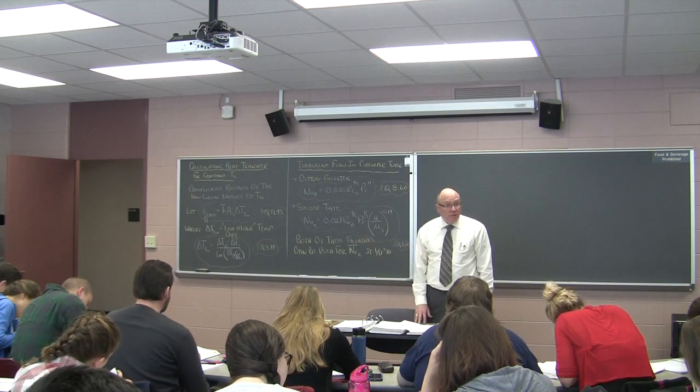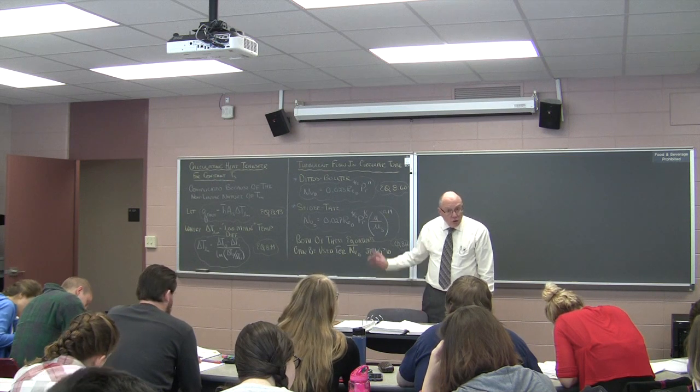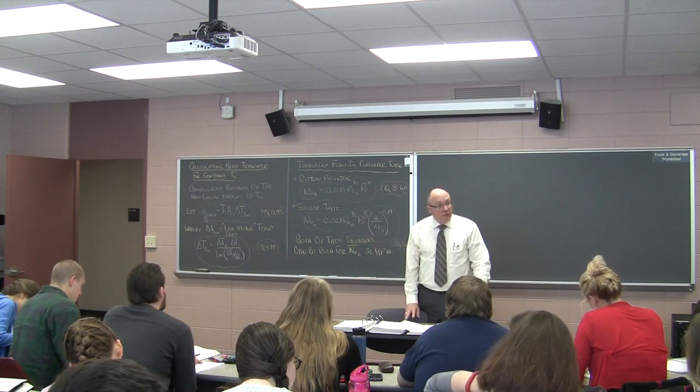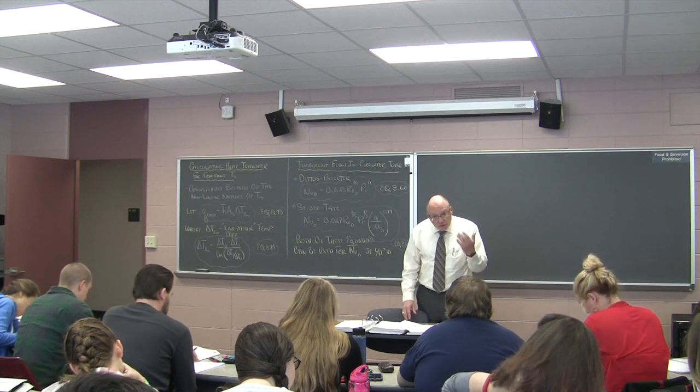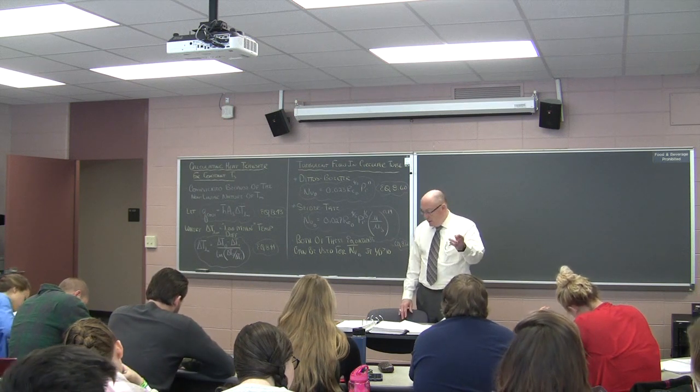So these are your go-to equations. Any questions? And remember, you're going to use Dittus-Boelter unless I tell you you've got large temperature variations. And that's the key word to jump you in,